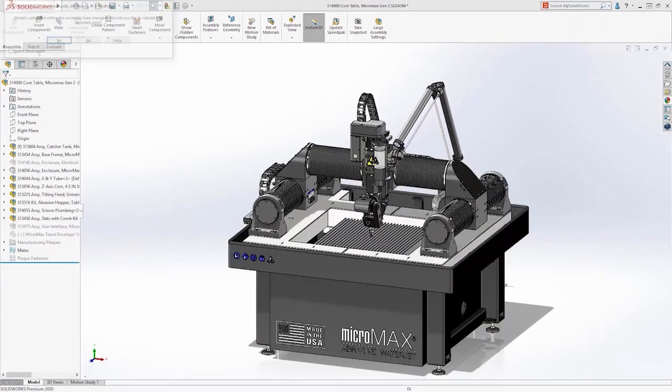What's also great about this is that the envelope is going to stay up to date. So if that component changes, that reference will force the subassembly that we were just mating in to update as well. So this is very powerful, very handy. I definitely recommend taking advantage of envelopes so that you aren't working in your top level all the time.